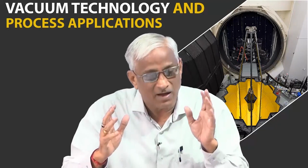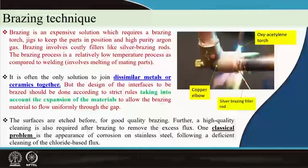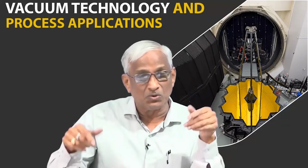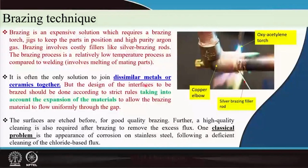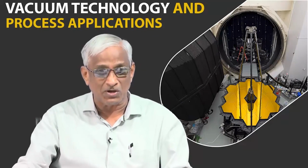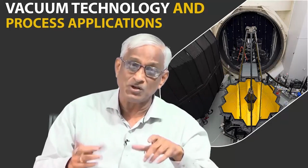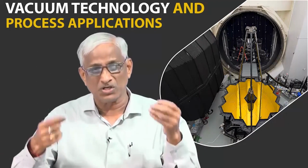So, all these things are very important, and it is worthwhile spending that much money, because you cannot afford to have welding at that place. So, naturally you have to go for brazing, and when it comes to ceramic to metal brazing, such complicated things, you have to follow certain strict rules with respect to vacuum compatibility etc. And when two materials have two different expansion coefficients, the joint may be made, but when it is cooling down it may crack. So, all those things you have to take into account. With brazing, you have to clean the jobs before, and you have to clean afterwards to remove the excess flux. Otherwise, you will start getting erosion and corrosion issues.